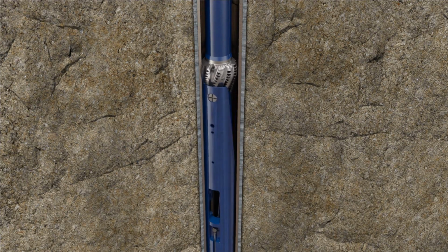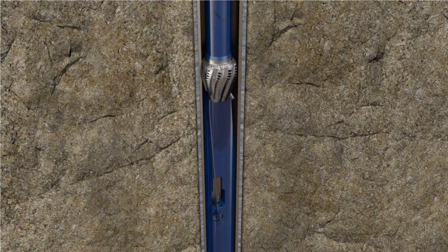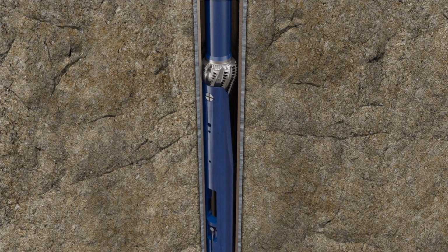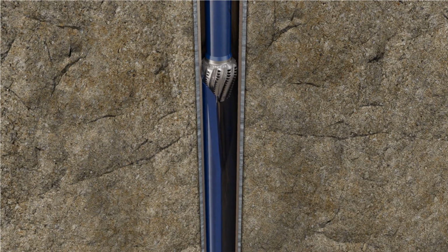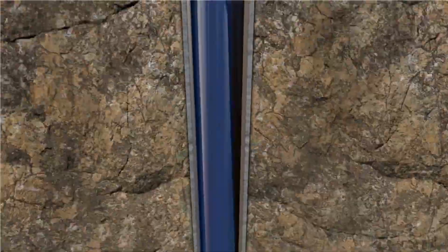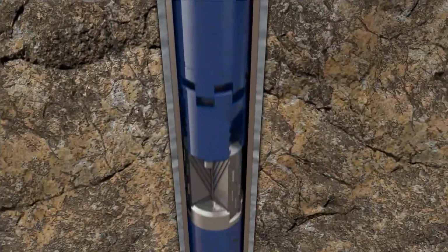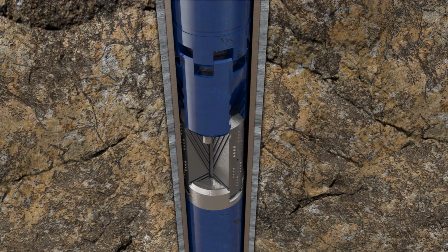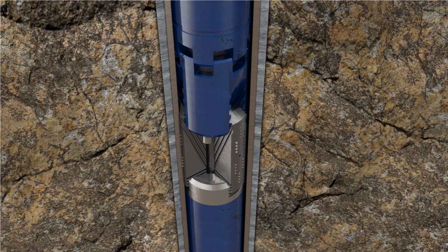From the nozzle of the mill, a hose carries hydraulic fluid from the running tool to the anchor at the bottom of the assembly. Before setting the whipstock, it needs to be oriented so that the BHA kicks off in the right direction. Once this is done, the anchor can be set. This is normally achieved by increasing the flow rate until the bypass is triggered, which directs pressure to the running tool. Hydraulic fluid pressures up in the anchor and the dogs are extended out to lock against the formation.